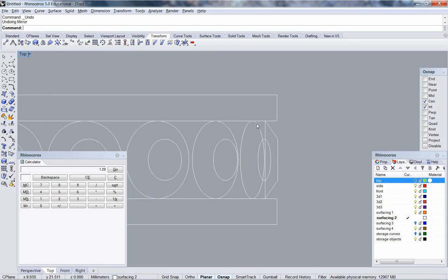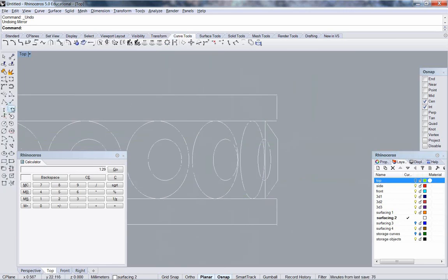Okay. I need to draw the ramp of this stone, of this crown. That stone's crown. So, I'm going to do a straight line. Now I could do this by eye using near snap. You know, come up with something pretty good. But Rhino actually has a curve tool that allows you to do that much more precisely. Line, same command, but now I'm going to hit tangent and 2 curves.